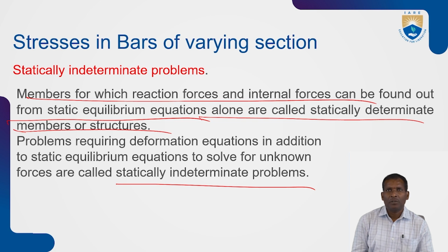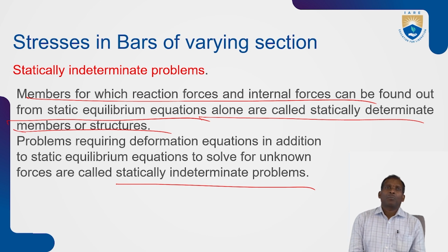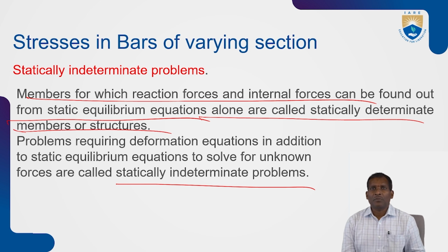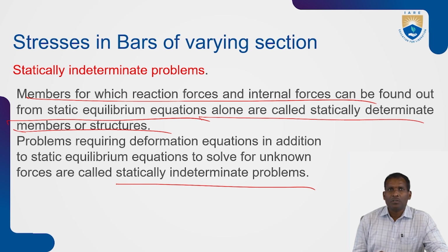So statically determinate problems means the internal forces and reaction forces can be found out from static equilibrium equations. The problems requiring deformation equations in addition to static equilibrium equations to solve for unknown forces are called statically indeterminate problems.